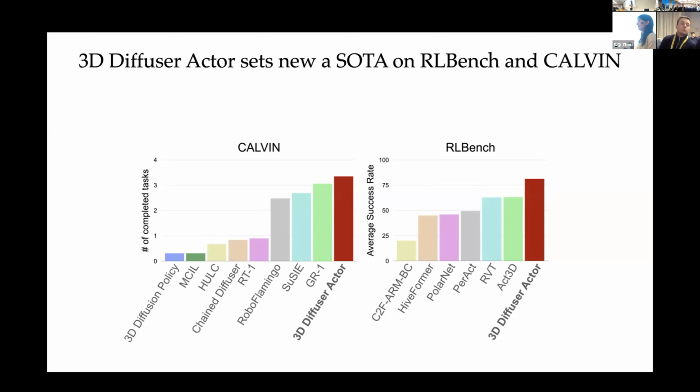Another very important detail is that we do task space control, right? So you predict your key pose in the coordinate system at the robot base. There, this doesn't work. You need to use the end effector coordinate system, which translates and orients with your gripper.